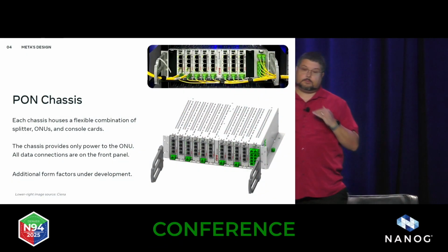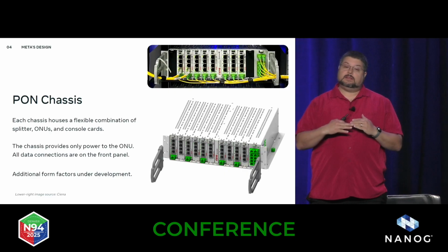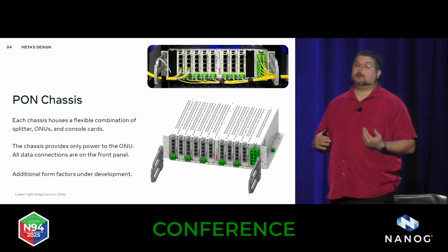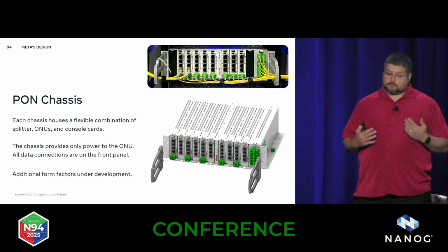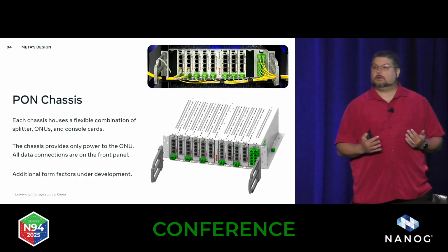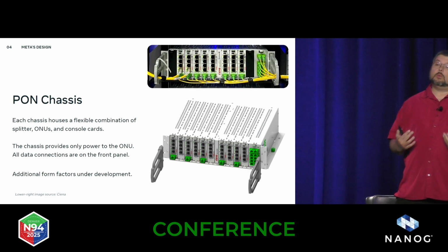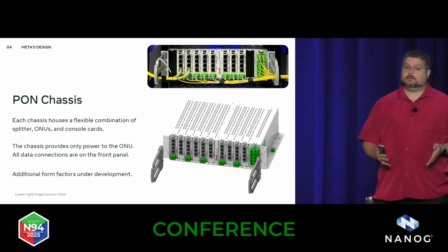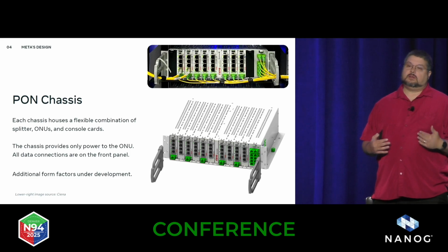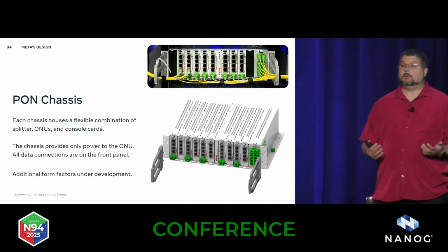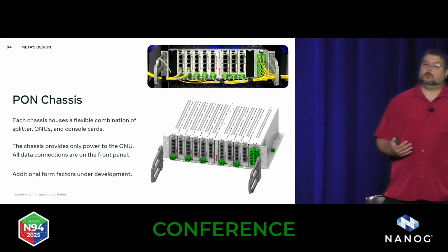Because of that, when we designed the canopy, actually, one thing you'll note, I'll go to that picture really quick. One thing you'll note here is the cable management crosses the cards. We had to preserve our vertical space to get the maximum amount of footprint, so we did not put horizontal cable management to keep the fibers out of the way of the cards. We did this intentionally because of the high expected reliability of the components in the ONU and console cards, so that we know that when we do have a failure, we actually will have to pull out adjacent cabling as well. But we're willing to take that risk on, given what we expect to be the low failure rate of the cards. Also, in this type of equipment, the most likely failure opportunity is going to be at initialization, right? A card that had a manufacturing defect and won't come up or was damaged in transit. Once operational, we're expecting that failure rate to be quite a bit lower.